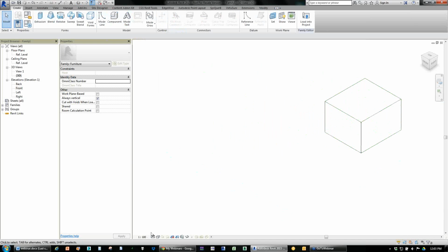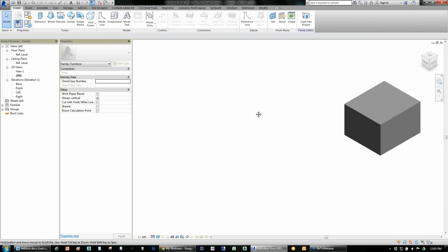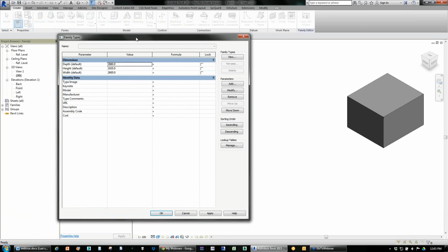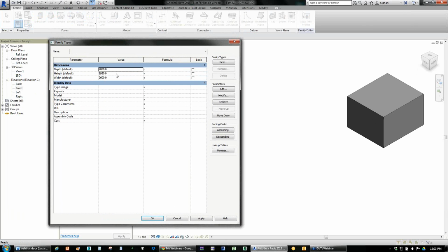And that effectively is, make it shaded, there you go. So I'll just pull that over to the side so you can sort of see it there, and then I can simultaneously open up this dialog. We can see it working there. Okay. Very quickly, before when I said that this was an instance parameter, you'll notice that next to that it says default. That's how I know it's an instance parameter when I open up a family.